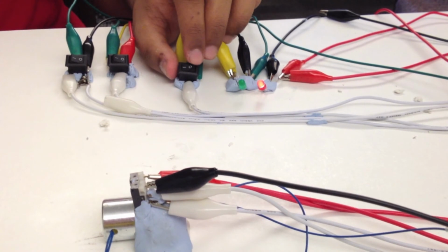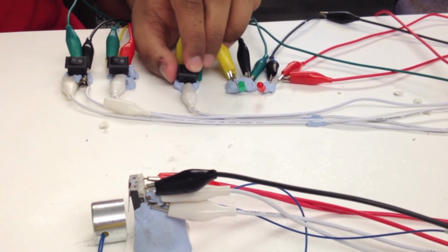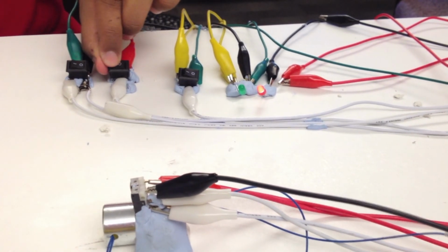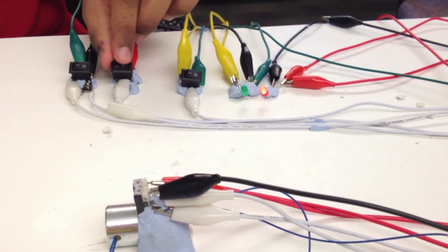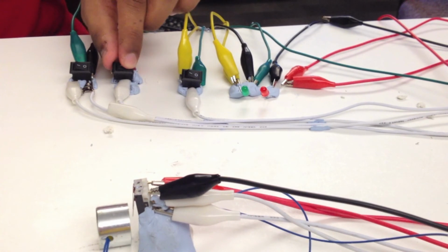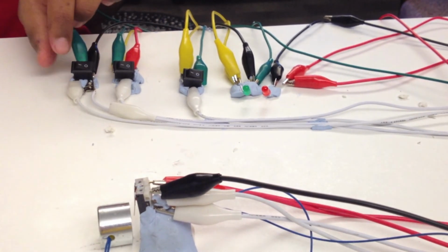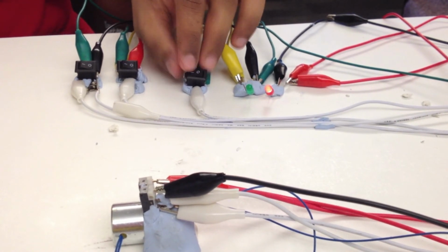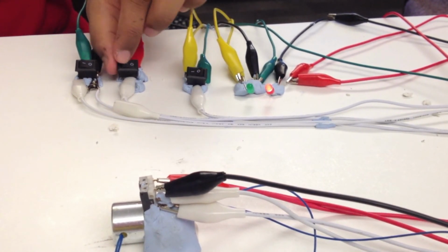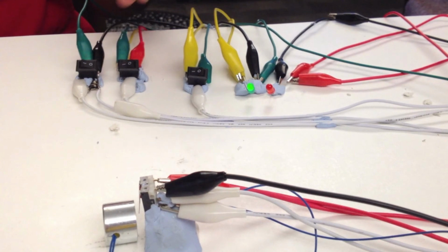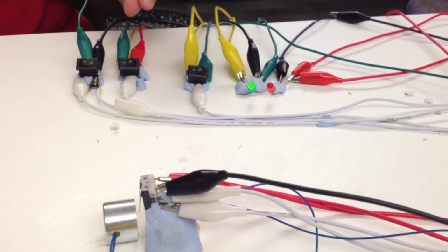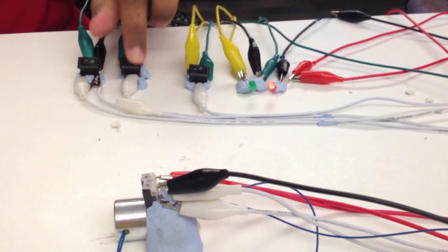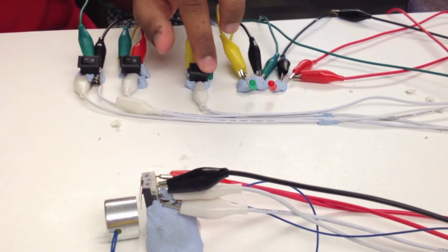Full adder. First, the carry-in bit is set to 0. An input of 0 0 0 has a sum of 0 where both the LEDs are off. An input of 0 1 0 has a sum of 1 shown by the sum LED as on. Input of 0 0 1 also has a sum of 1 and the sum LED is also on. An input of 0 1 1 has a sum of 2 or 1 0 in binary shown by the carry LED as on and the sum LED as off.